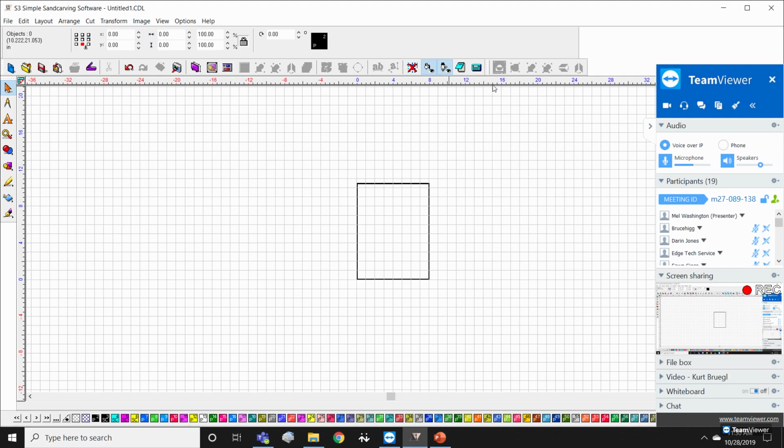the toolbars. One last thing about the toolbars, these are dockable tools. So if for some reason you wanted to have your text tool out where you could get to it all the time, you can bring that out onto your work surface and just click it and do anything that you would do from clicking it here. If you want that toolbar to go back to where it belongs, just click the text tool and it'll redock itself for you.